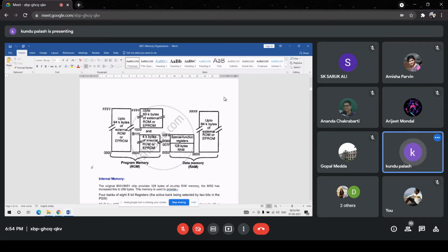So this part is the diagram for program memory, where the microcontroller application code or instruction compile code will reside, and this diagram is meant for the data memory. So this data memory again can be partitioned, but generally internal data memories are used for application programs and usage by the internal GP registers.